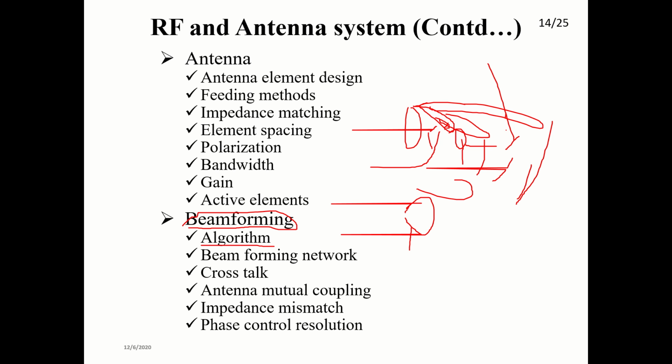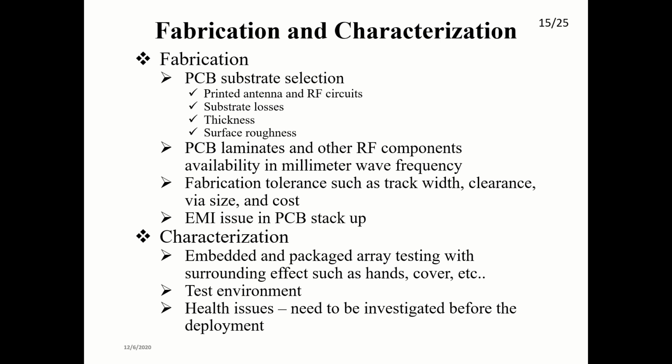Whether you are exciting the ideal phase, for example, if your design phase is 120 degree, it should be excited with the 120 degree phase shift. Otherwise, your beam direction may slightly change. So that's why it is very important.